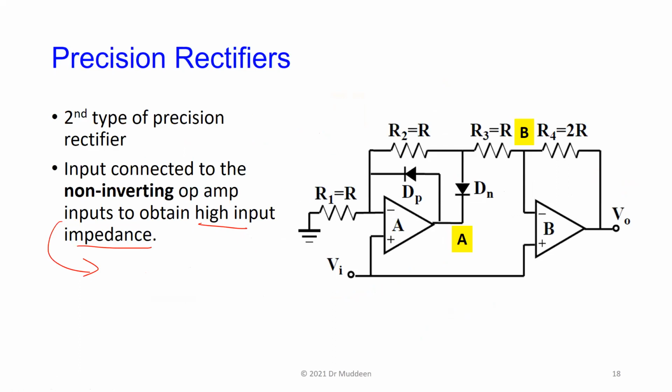So when you send it to the non-inverting input, remember now, because of the characteristics of the op-amp, although here is now the earth point, here you're trying to match the input voltages. So what is happening is that the input impedance is actually seeing whatever is the input impedance of the op-amp, which typically is a fairly large value. This now tends to run into the megohm side. So it's not fully dependent on the resistors here, but what you're seeing coming in there will be in the megohm sort of range.